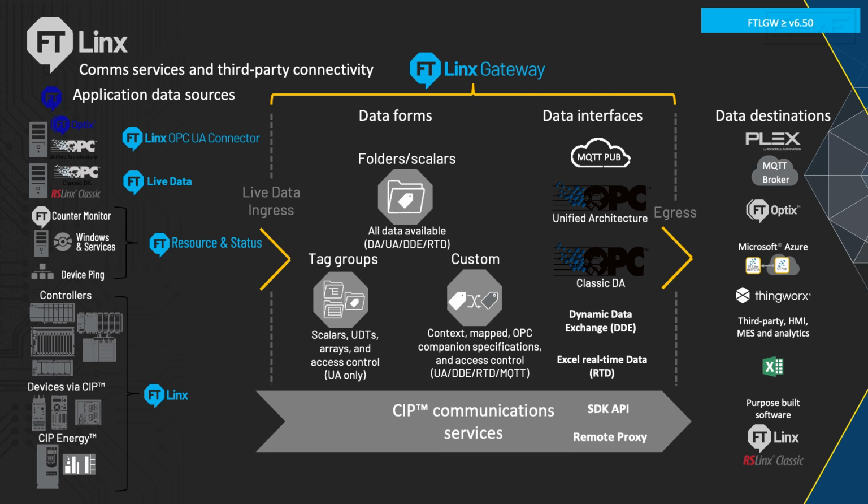What a companion specification is meant to do is work with the machine vendors to define these specs and the data points associated with a filler, a capping machine, a bottling machine, or whatever it may be. If they adhere to that companion spec, it becomes much easier to integrate your line no matter who your vendor is, because those are the data points the OPC UA servers expect to get in and provide out. That's what companion specifications are really meant to do.